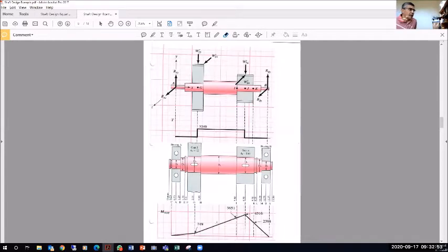And again, this is very important, and I mean to put it all on one page, where I am seeing the proposed design. Then I am showing the critical locations, and you see these dotted line extensions. I'm showing the torque diagram, and I'm showing the total moment diagram, because this is going to dictate what my starting point is and how we're going to move from one section to another as we are designing this shaft.